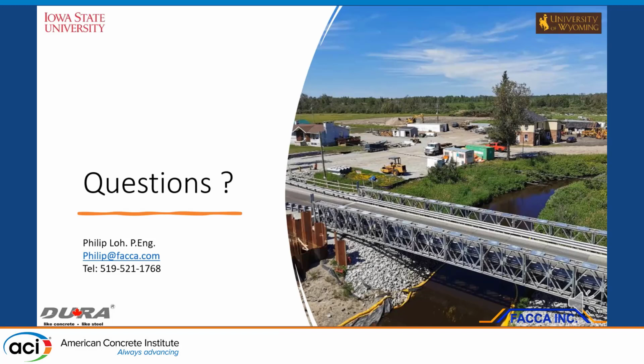The end bearing component, we don't have a good handle on, because that's what the pooled fund that Philip mentioned is for: to collect more data so we can come up with new resistance factors for UHPC piles. If you take the data that we have collected so far and compare the UHPC pile to steel pile at 100 kips of load, the costs are pretty comparable. My hope is that we get better if we can get more refined resistance factors.